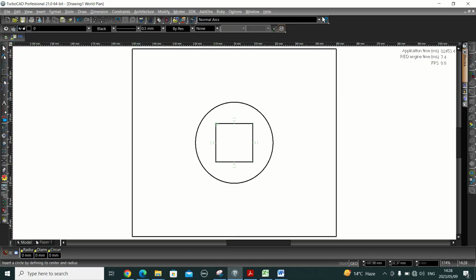Make sure your circle tool is selected. Press tab. X will be highlighted. On X, put 40. Y is 24. Press enter. Move your mouse around. You will see that you have a circle starting there. Now, the diameter, press tab until diameter is highlighted, is 12. Put 12 there and press enter.